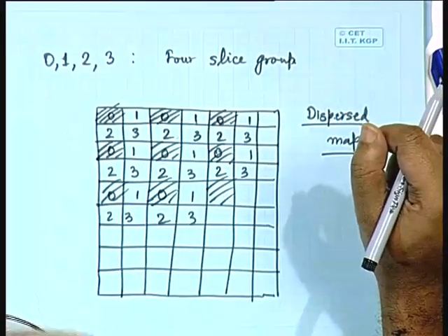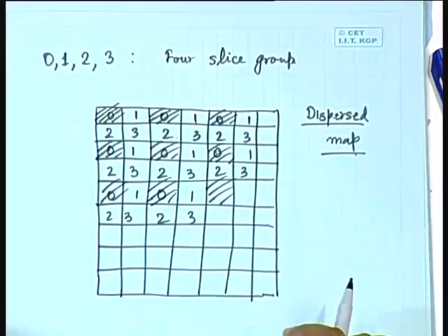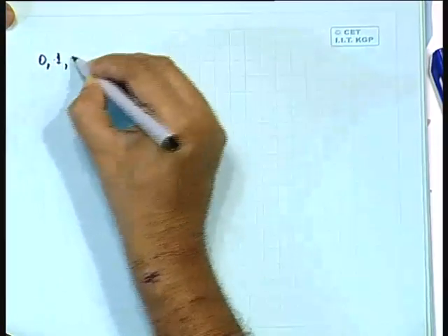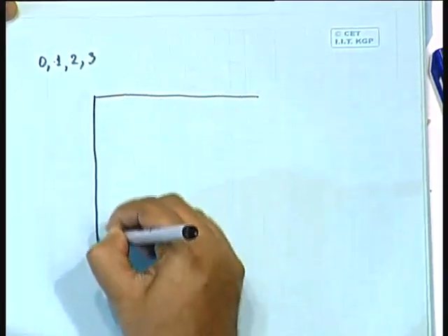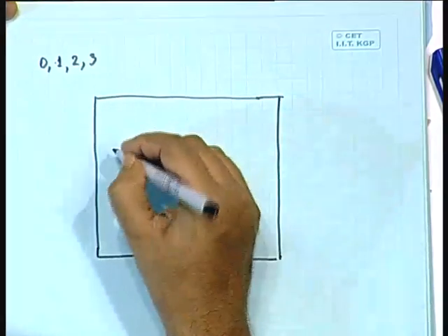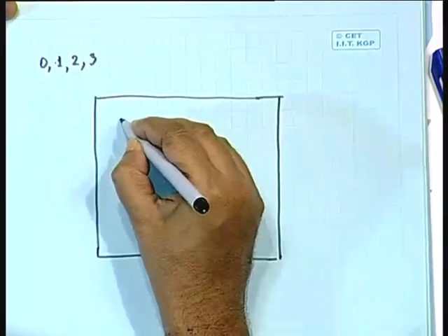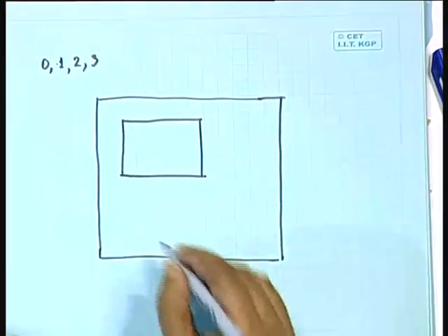And there could be a realization of slice groups in a different way, as I was telling you that slices are very effective for encoding the foreground and the background information separately. So, you can define the slice group something like this. Again, take 4 different slice groups, and let us number them 0 to 3. Supposing this is the frame that we have to encode, we can say that this set of slices forms slice group number 0.